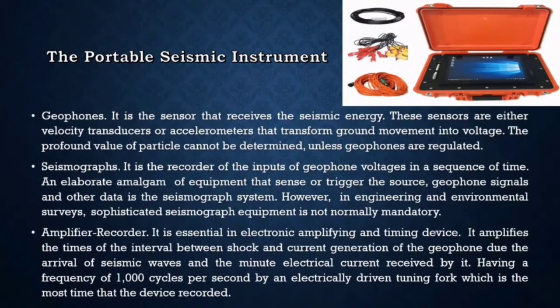Seismographs. It is the recorder of the inputs of geophone voltages in a sequence of time. An elaborate amalgam of equipment that senses or triggers the source, geophone signals, and other data is the seismograph system. However, in engineering and environmental surveys, sophisticated seismograph equipment is not normally mandatory.